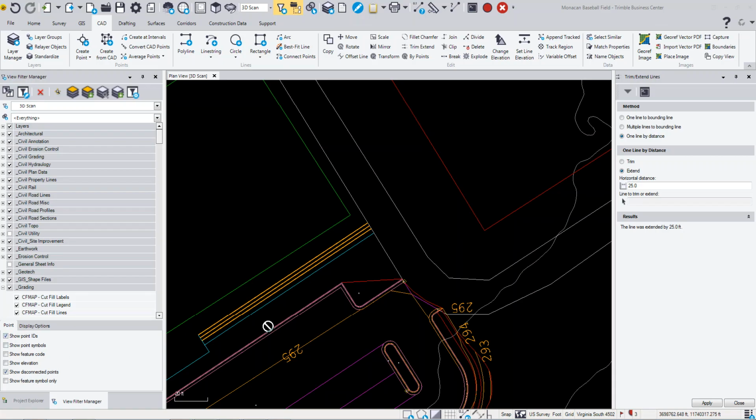Now if I want to trim it by a specific distance, or I want the line to be a total distance, there is a way you can hold the shift key down and select that line, and that line tells me that it's 121.8. So what I need to do is, let's say I want this to be 100 feet exactly. Well, then I could come in here and say minus 21.8, or I'm sorry, actually minus 100, because I want to shorten it by 21.8, right?